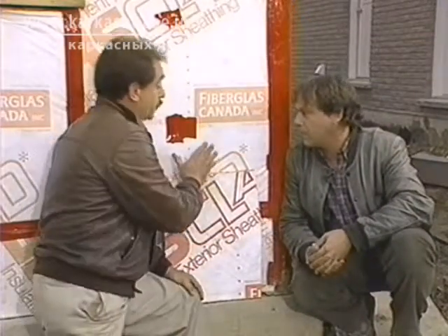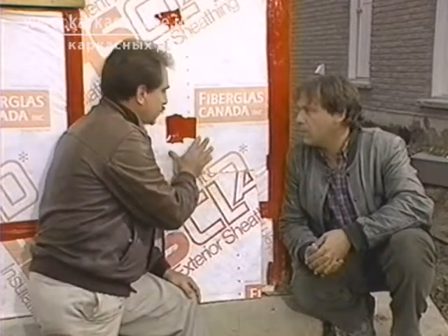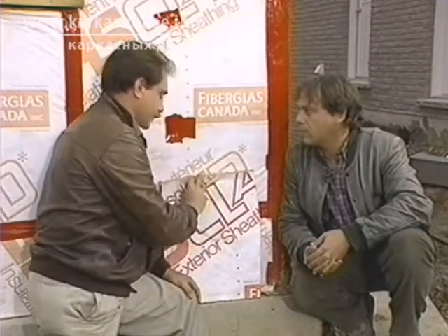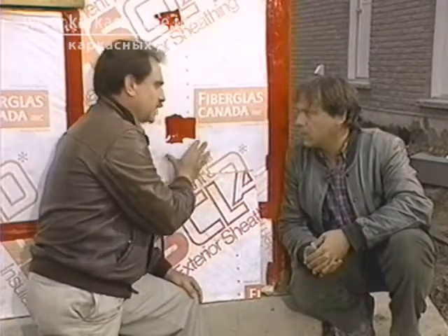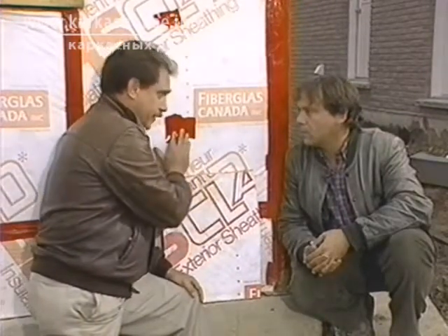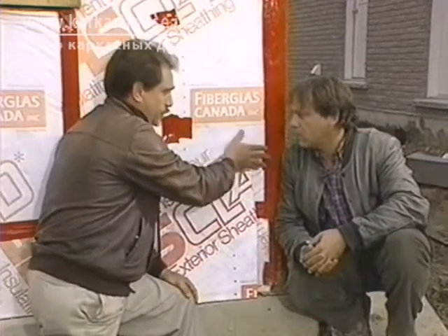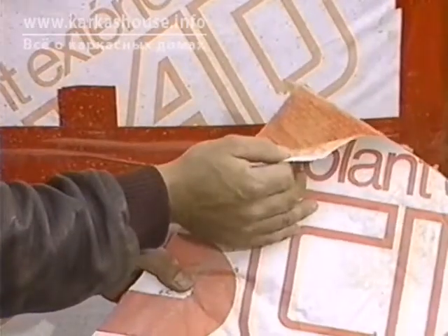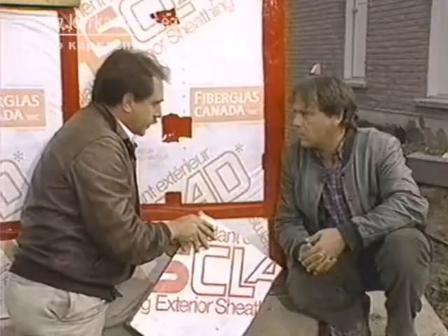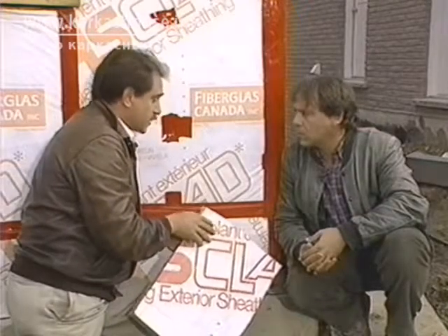Well, I brought you out here to see this paper. Now, this paper is not here just so that the manufacturer of this material can print his name on it. The purpose of this stuff is to act as a wind barrier, which is why it's been very carefully taped at holes and joints, at corners and so forth. But it does breathe. It permits water vapor to exit from the wall cavity, so if any gets in there, it can breathe to the outside. This material, the paper, is called Tyvek. And in this particular case, the Tyvek has been bonded to an insulation material, an exterior sheathing called glassclad.